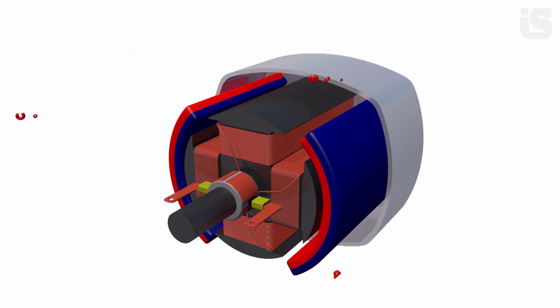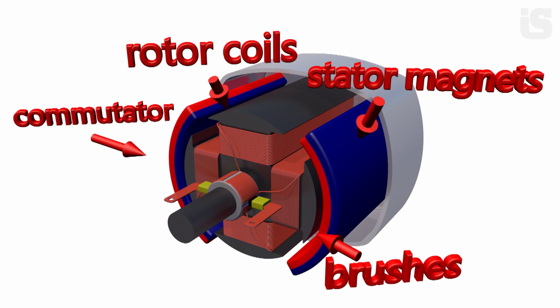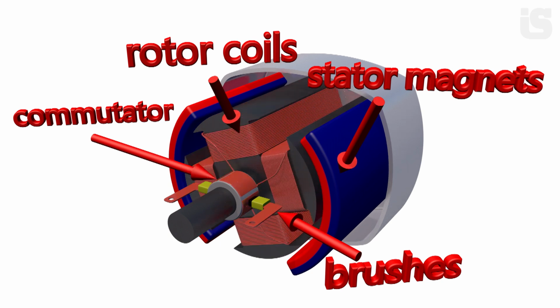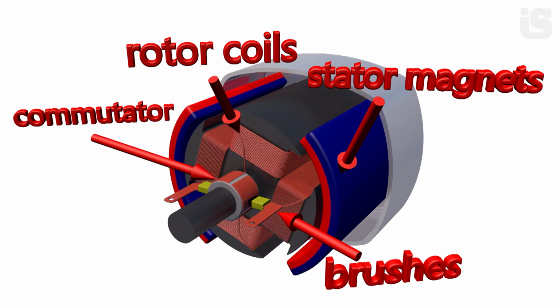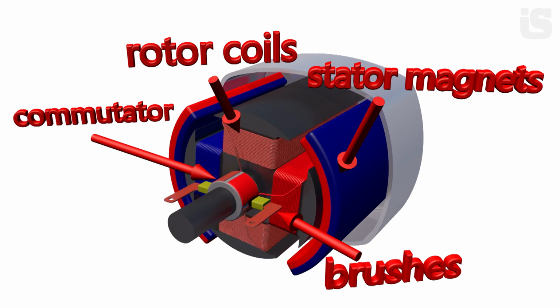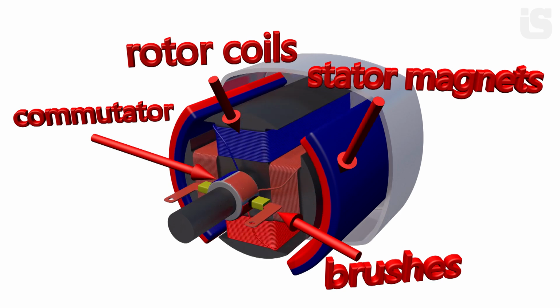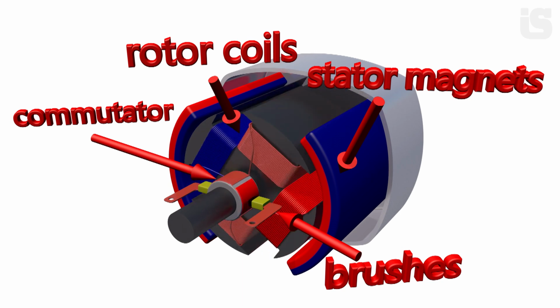Let's take a look at an electric motor. It has a stator. These are permanent, immovable magnets. They are located on the sides, along the body of the electric motor. The body also has brushes for contact with the commutator ring. The brushes are immovable. They mechanically switch the winding segments, thereby ensuring the rotation of the rotor.